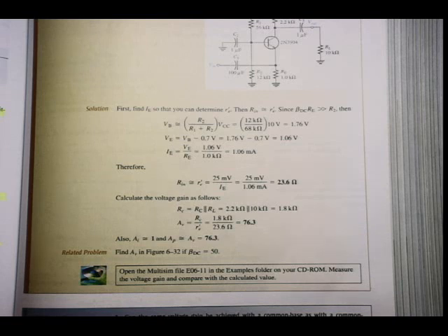You're going to see that. So you have to be able to recognize the configuration of amplifier. Then of course you also have to know the characteristics of that amplifier. Alright, and they also give us the value of beta DC, which is 250. If I look at the amplifier, I will see that input is applied at the emitter, the output is taken from the collector, so the base is AC grounded, making this a common base amplifier. So then I can calculate accordingly.